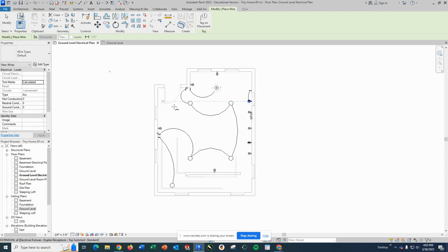And what you're going to want to do is do this on all of your levels. I have a basement level that I can do this on, but basically outfit the entire home so that you are all good to go. If you have lofts and stuff like that, that's great. What we will do later on when we build a sheet with this is we will actually put all of the views on the same sheet, which will be perfect.